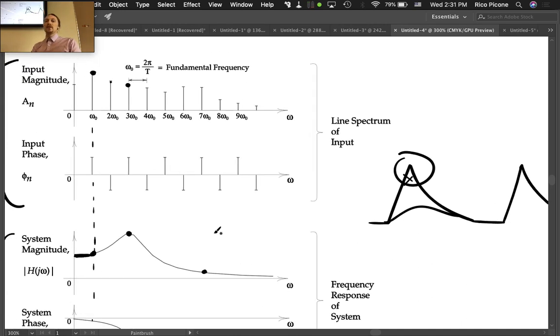If you want to measure this, you have to change your measurement system to shift all of this stuff, the resonance, and then the high frequency roll off here. You have to shift it to higher frequency, okay? So you need a wider band for your measurement frequencies.